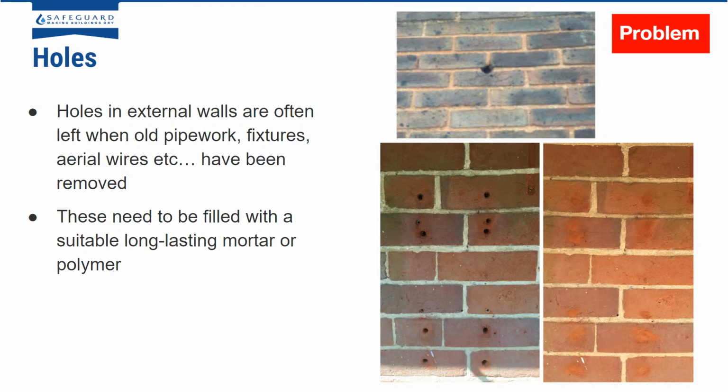So the two pictures at the bottom there were of brackets that were removed, and simply in those situations, it was filled with a polymer mortar, such as XR mortar, and then a sprinkling of brick dust was put on top to match it into the brickwork.